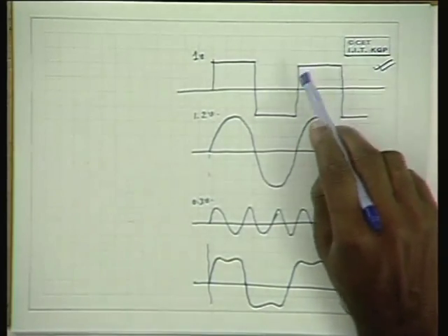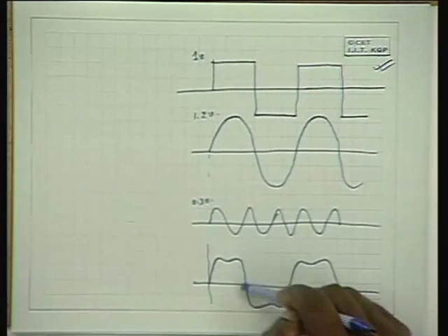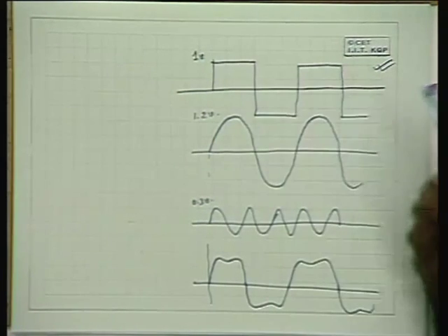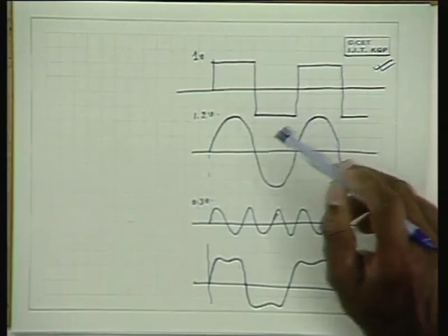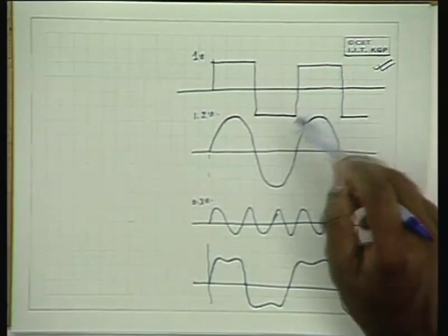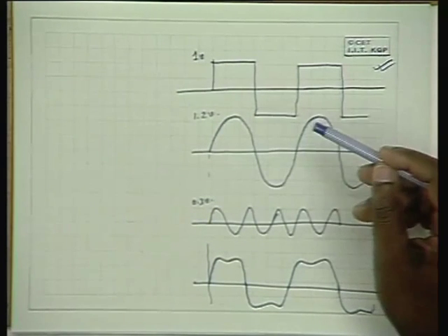Asymptotically, when you consider an infinite number of components, the error almost tends to 0 in this particular case. Yeah, there is a doubt somewhere. So, why are you always taking the odd harmonics? In this particular case, the symmetry of the signal is such that when you add the odd harmonics, it makes up the signal. If you try to add the even harmonics and find a solution, you will find that the even harmonic amplitude is 0.